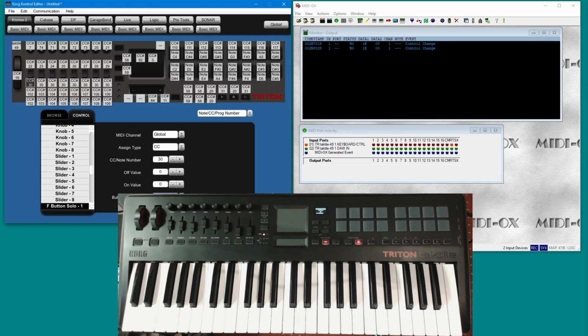Let's talk about momentary and toggle. Momentary is that this button, this is programmed as momentary. This is exactly what you see. For one moment, it sends on and then off. In the toggle mode, it will generate only one message every time you press and release. This is the big difference. Depending on your application, you have to decide if you want it as momentary or a toggle.